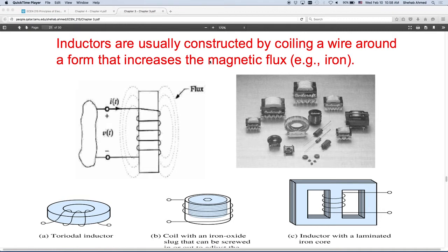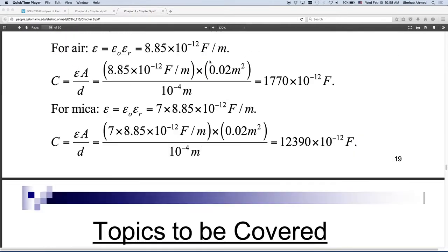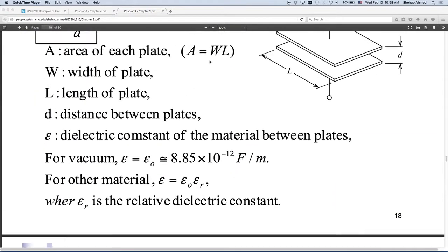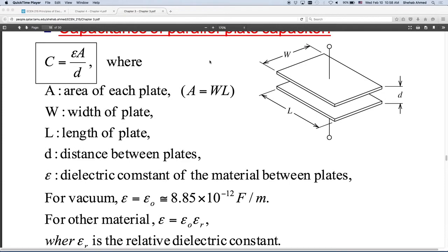So anyway, let's get started. We wrapped up last time when we were talking about capacitors. I think where we stopped was we said that you can design a specific capacitance based on selection of the dimension or area of the plates, the distance between the plates where the charge is deposited, and the dielectric constant between the plates, right?